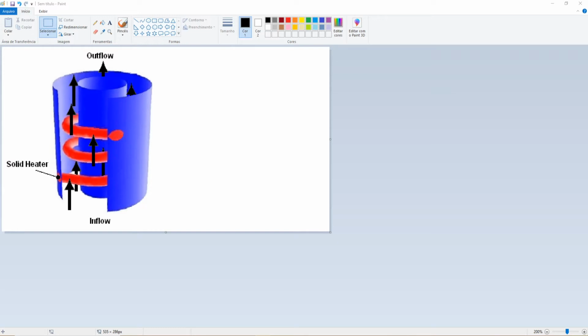So what is the purpose of this tutorial? This tutorial demonstrates the capabilities of CFD to model conjugate heat transfer, as well as differences in conductivity between the extremities of our coil. There's going to be a fluid domain for the water, and we're also going to have a solid domain for the coil. The fluid domain, like I said, is this ring region that will envelop the coil,